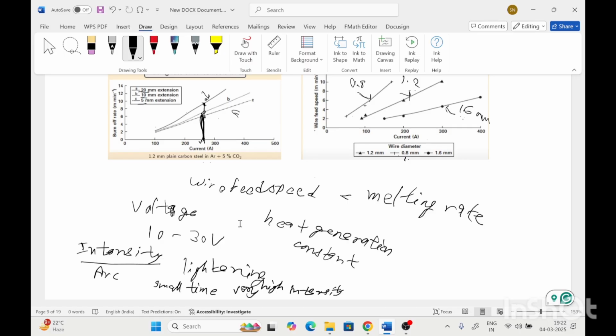The welding bead should be uniform. If we have these two work pieces, then for a given length, the weld width should be uniform. For any process we will require this. So this is the first requirement: the welding bead should be uniform so that we can get good mechanical properties of that welding joint.